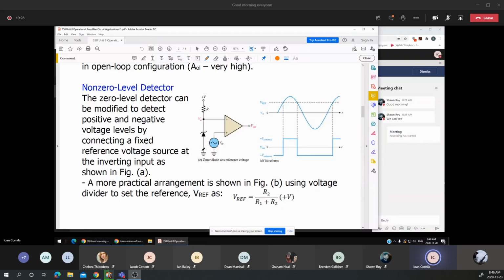That's a very hard way to get a Zener diode that has the reference voltage or the VZ as 5.25. Usually it's 5.1 or 5.8. If I need any other voltages which are between those values, it's very hard to obtain these values.